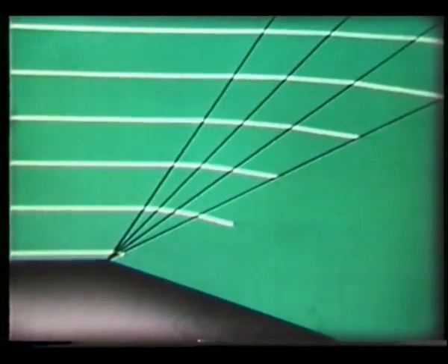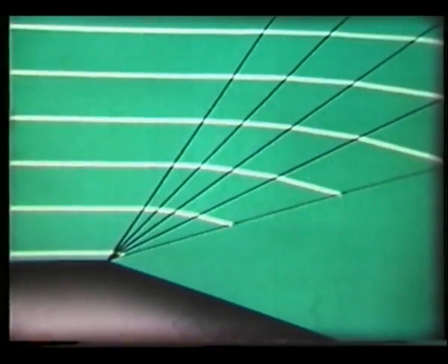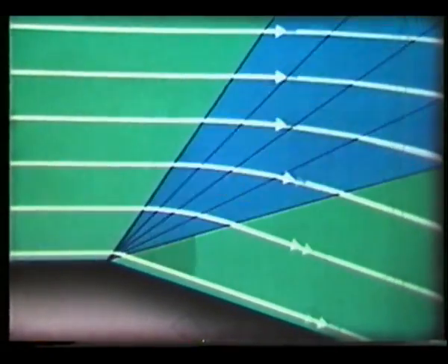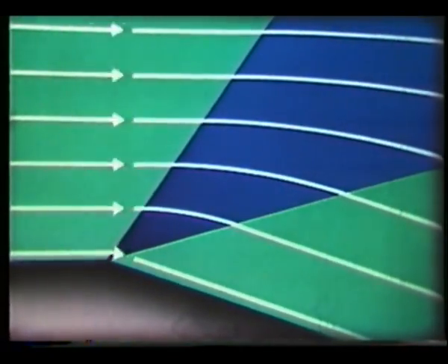The influence of the corner is at once felt along a new Mach line, and the streamlines bend again, and so on. An expansion at a corner can be looked on as a series of tiny changes in direction, pressure, and speed. The expansion ends at the Mach angle corresponding to the final speed and direction of the flow. So it is confined to a fan-shaped region between the first and last Mach lines.